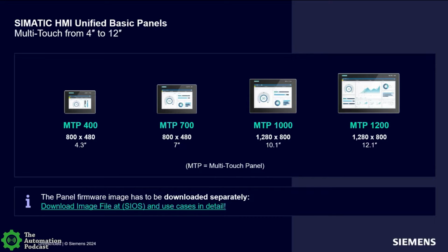If you get a new computer at work, you could just install TIA Portal 19. You don't have to go back and install, and I'm thinking about the original Unified Comfort Panel, you don't have to go back and install 16, 17, 18, and 19 to support all the different Unified Comfort panels you have out there. You can just install 19, and it's not going to automatically rev your panels all up to 19. It's going to work with those that are out there. Correct.